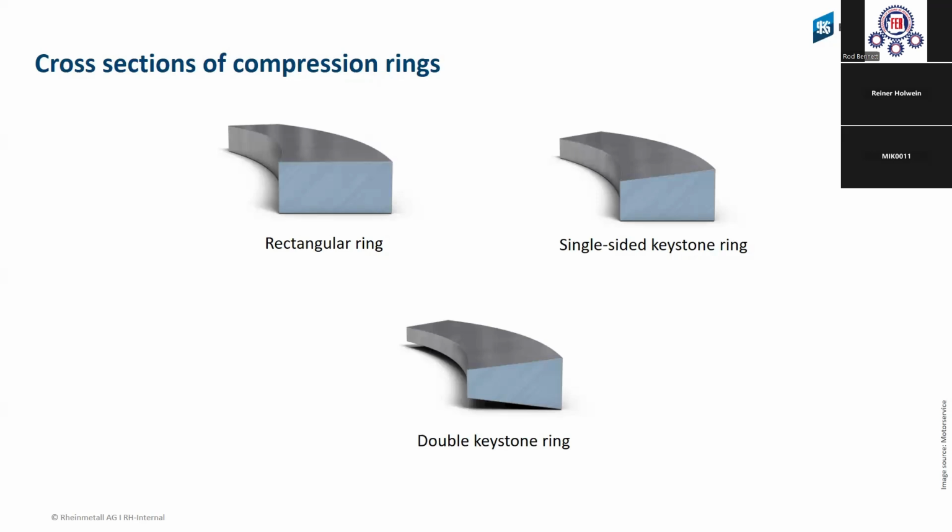You remember when I showed you the movie, when the piston goes up and down, and we have the thrust and the anti-thrust side. That means we have pressure only on the left skirt and the right skirt. In the line of the piston pin, we don't have direct contact. There is no pressure and anti-pressure side.